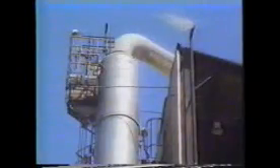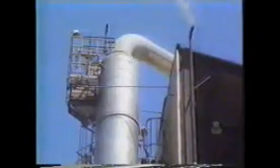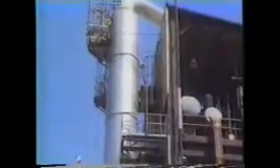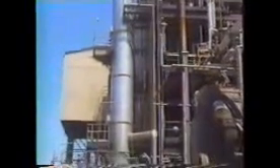As it does most of the time, this startup came off without any problems. However, sometimes problems can occur, and you should know how to deal with them. Let's take a look at some of the things that can happen during startup. Generally, the biggest problem in a vacuum column like this is a leak in the vacuum system. Any change in the vacuum will cause a change in the temperatures and pressures in the column. Such changes could greatly reduce the efficiency of the system or even stop the distillation process completely. If this happens, the system may have to be shut down until the leak has been located and repaired.